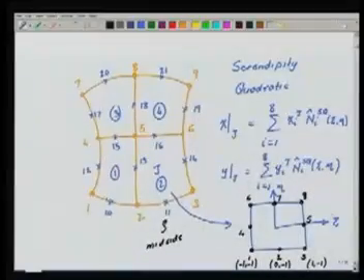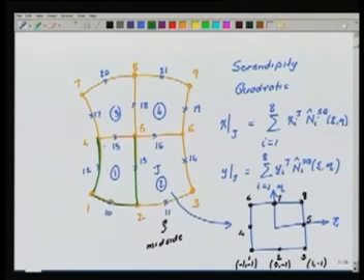If I do this kind of a fit, where I am taking more points lying on the curve in order to represent the geometry of the element, then we should do better than what we had done earlier, and you will get a very good fit as far as these edges are concerned. There will be errors if this curve is not a perfect quadratic curve, but that error will be small. So the geometry that the computer sees is much more accurate than the geometry we had earlier with the bilinear map. That's why we should use a higher order map.